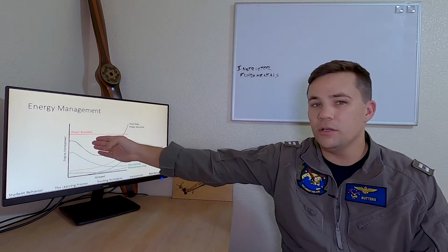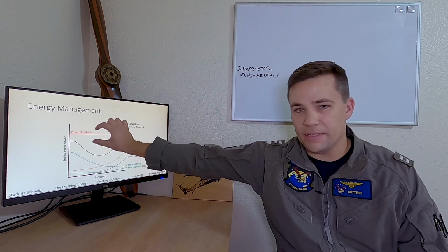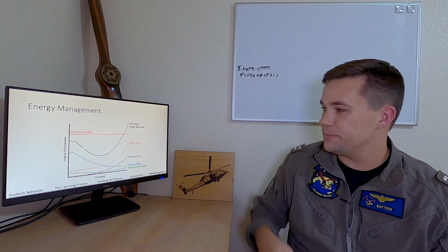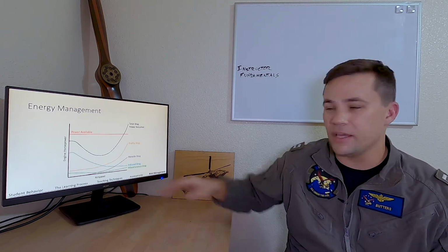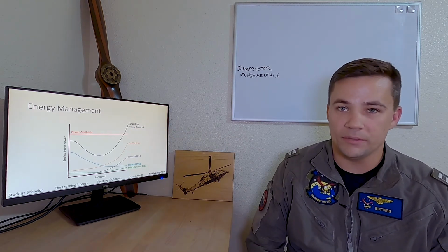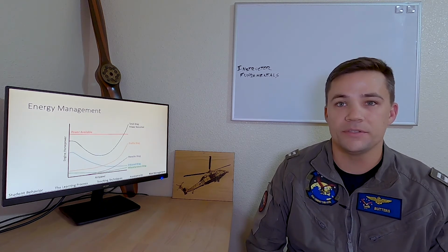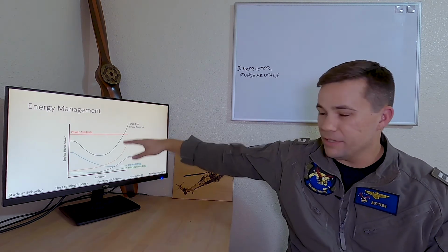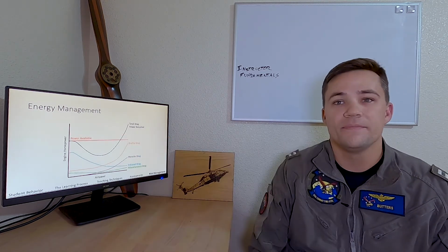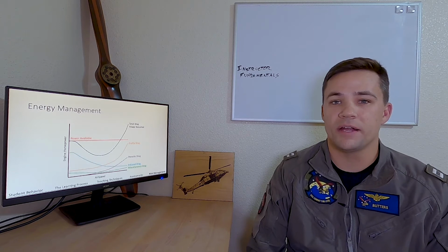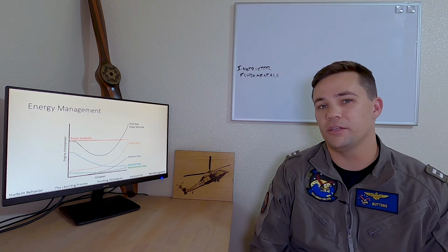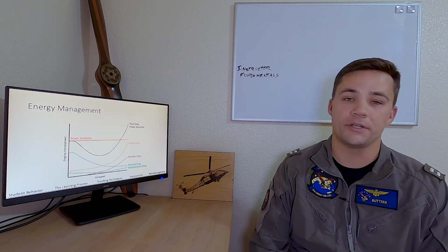It's the other direction that you have to worry about. If you slow down, you'll now have less power available on that side, and that can cause you to slow down, especially if you've got a fixed collective setting that isn't necessarily at our max power available. But where you can really get into trouble is if that max power available does start to come down. So if you're looking at a situation here, basically we're in an environmental condition where we only have essentially the exact power available required to hover, no margin above it.